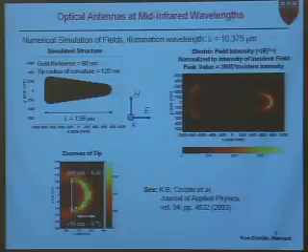And if we zoom in at the end of the tip, then we see that these fields are confined to dimensions that are roughly 260 nanometers in this dimension, or lambda/40 at the wavelength of operation, or 150 nanometers, or lambda/70, in the other direction. And these dimensions correspond to roughly the radius of curvature at the end of the tip, which was chosen to be 120 nanometers, by about twice the radius of curvature. So this is telling us that this structure is really able to confine fields to dimensions that are given by how sharp a structure we can make, rather than any sort of wavelength limitation.